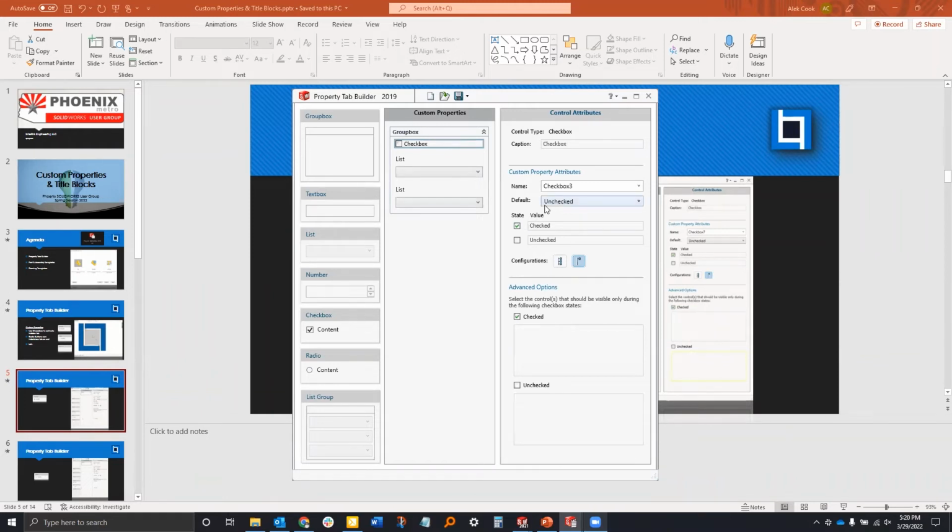If I come to this checkbox, the name here is the variable that's going to be referenced on your drawing title. If it's checked, it's going to display that name. So when it was checked, it displayed the name inches. And I'll show you ours once it's done, but it's kind of nice to see what it looks like when it's blank. Now, when it's checked, if I want a text box to display like ours, then I select there and it says list 4 is going to display.